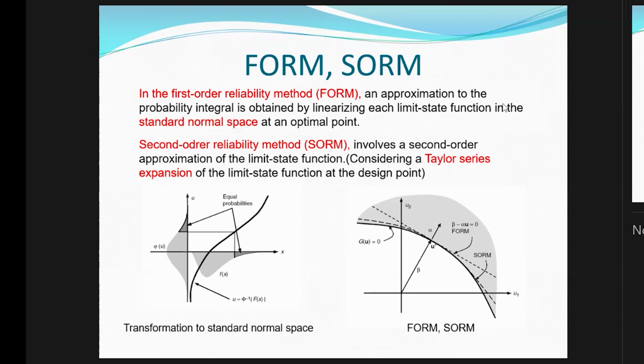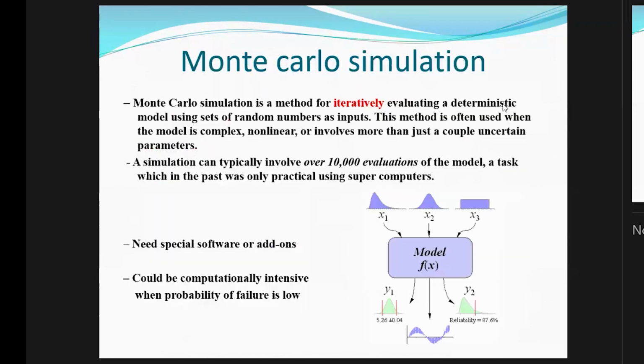So this is how we can integrate our limit state function and obtain results where we fall down. It is actually not one analysis; it is multiple analyses we perform. This has application in first-order and second-order reliability methods in earthquake engineering, where we have an explicit limit state function. We know what stresses make our structures collapse, and it's easier. In some other analyses, it's not so easy to do.